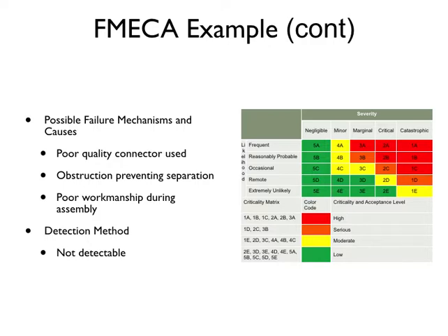Given that this would be done with a FMEA style analysis, the RPN would probably have had a value of 10 for the probability of detection, which would have driven the risk up. So it's important to note those differences in the two styles of analysis, because in this particular case, it was a disadvantage to do it with a FMECA style analysis.